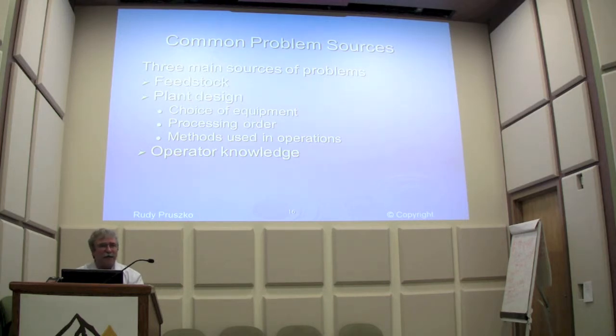You know, a lot of times people don't understand the process. Get in the lab, make these small little batches, make mistakes. When we taught our workshop, we would actually have you make a batch with too little methanol, or too much catalyst, or too little this, or too little that. And it always turned out terrible, but at least people got to see what happens. And then when they get back and run their own plant and they see the same thing happen, they know, oh, I know what I did wrong here.